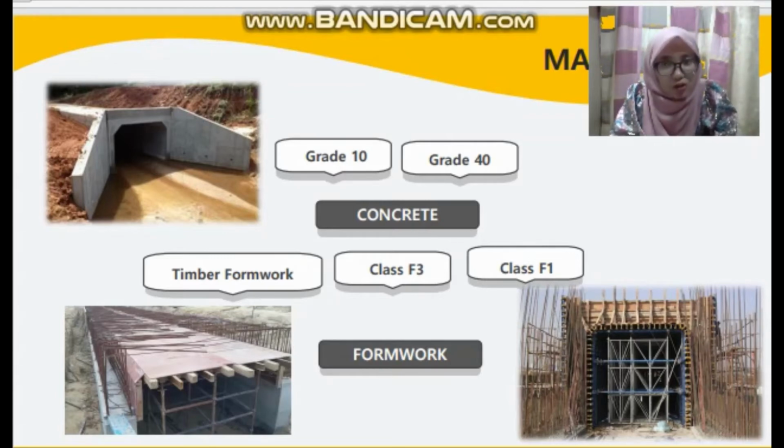The construction of the culvert in this project uses in situ concrete culvert. The concrete has been used to construct the wall, top slab, bottom slab, wing wall, and pile.